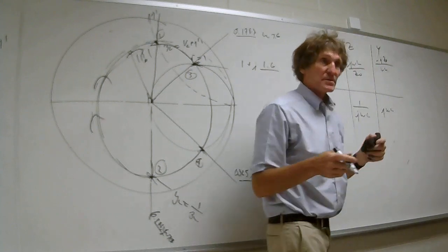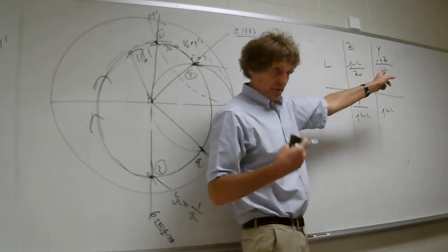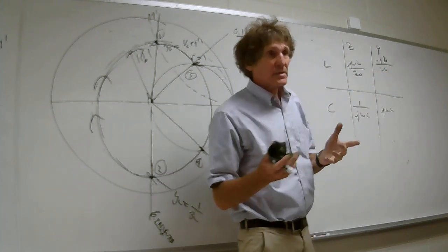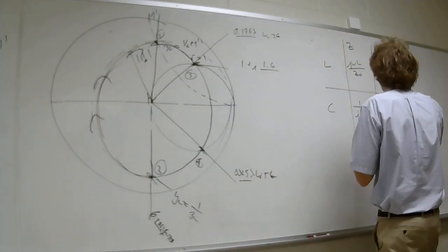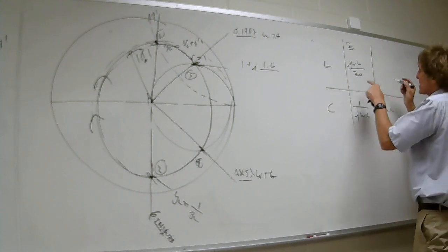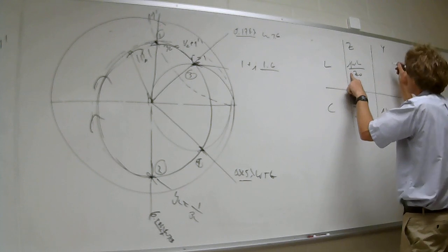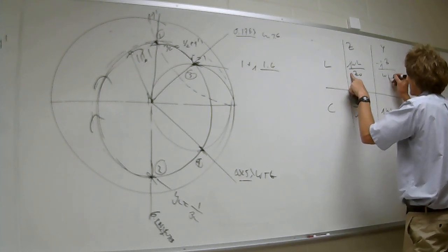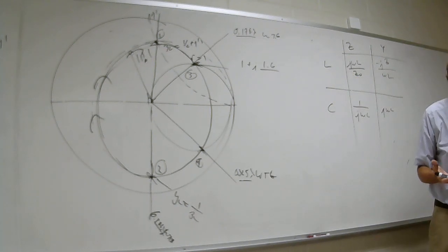Y'all follow me in this class? This would be normalized impedance, that would be normalized admittance. So it should be Y in terms of Y? Y is admittance, it's a symbol for admittance. Should Z not be in terms of Y, or is it still in terms of Z naught? Well, here's the deal. We could normalize it in terms of Y naught, but here, if you just take this and flip it, it becomes Y. So this, I leave it this way, it's minus J Z naught over omega L. It's still a normalized admittance, it's just flipping the normalized impedance.